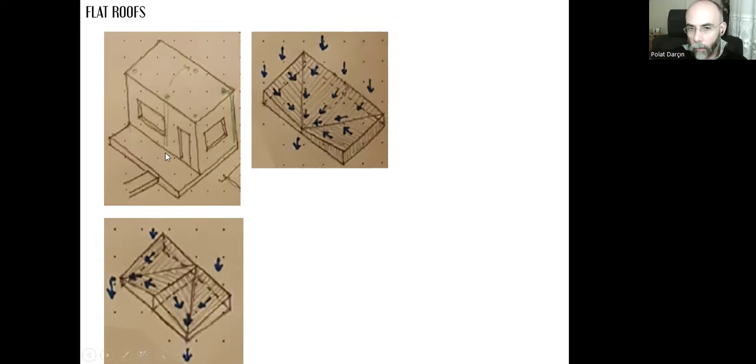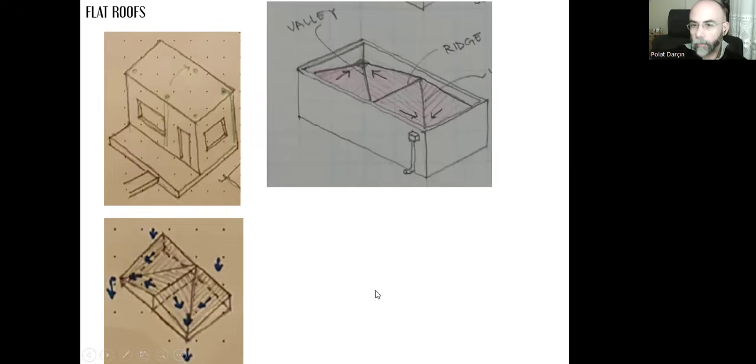Instead of this middle point, we can prefer the corners, two corners. This time we can change the design of the slopes like this. Again, we have two squares, almost squares, and this portion will be sloped towards this corner, and that portion will be sloped towards this corner.